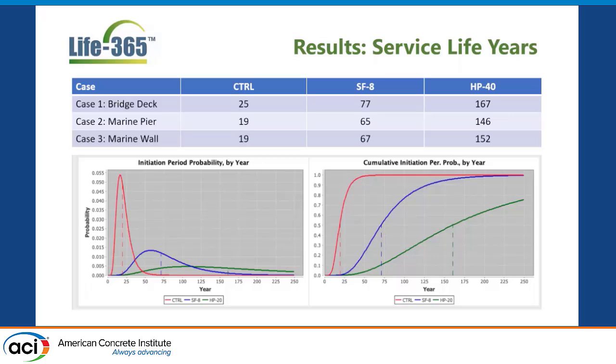I believe so. And that flips everything because, instead of the red line, 27 years, it's looking more like 12. And the same happens. So basically it's whenever the red, the blue, and the green cross the 0.1 mark. You're saying that it's the opposite. Yes, 10%. Because you want 10% of initiation, so 90% of your cases should not have initiated corrosion at X number of years. Can you do me a favor? Sure. Re-explain that graph.